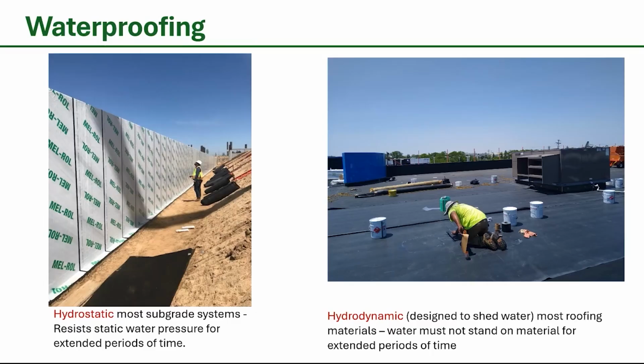It often requires a multi-component system. What you have there is a primer and a sheet applied membrane. It's lapped down onto the footing, which is a joint that is treated before you roll that membrane out. They've put a cove, a 3/4 to an inch cove of building mastic or material back there to seal the joint between the foundation wall and the footing. Then they've lapped that sheet applied over that. And at the end of all of that, they put a termination sealant on the end of that sheet applied membrane so that no water can wick in. So hydrostatic waterproofing is always multi-component. It always has some complexity. It always has a lot of belt and suspenders.